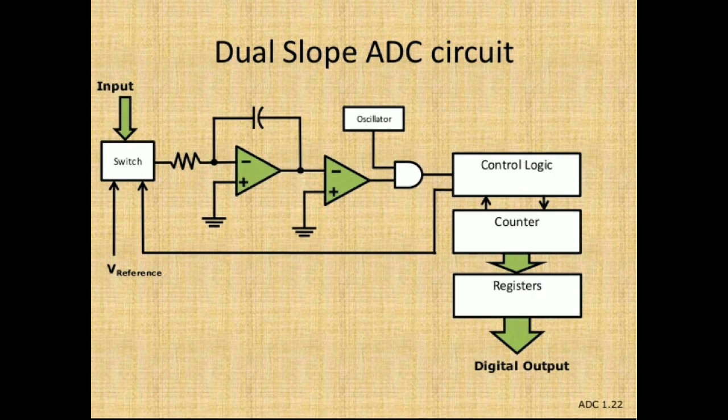In the second phase, the clock pulses generated in the first procedure, when the input was at the analog terminal, are counted by the counter. The counter continues to count the clock pulses generated, and the counts are stored in the registers. In the second half cycle the counter resets, and once again it is ready to count the second set of pulses. The stored values of the counters are held in the registers, which are connected to the digital output display devices that display the digital signals.